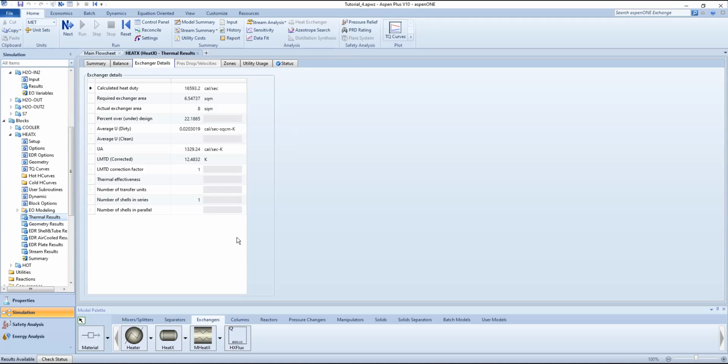And you can use this sort of utility to help gauge the capacity of your exchanger. And by this, what it means is that technically, if you're at the very initial design stage, you can reduce your area to meet the actual required area so that you maintain or reduce your costs. If you already have the heat exchanger and you're trying to optimize your flow rates, you can see that I still have 22% capacity, so I could maybe run more fluid through it or use this heat exchanger in a more efficient way. Okay.